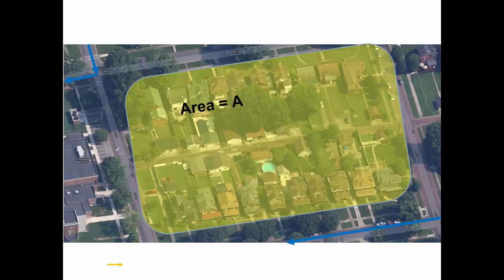In the homework assignment that I have, did I already give it to you? Yeah. I'm going to ask you to walk around in the parking lot that's to the side of the old engineering building. And sometimes the area is just as easy as roadway boundaries like this, but other times you have to identify what is the area that contributes by considering the elevation. And there may be a high point in a parking lot that allows water to flow one direction versus another. And so delineating the area or trying to identify what the flow patterns are going to be sometimes is a matter of visual inspection.